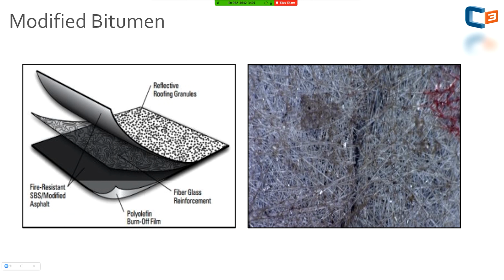So the composition there, you can just imagine that if hail struck this hard enough, you might have complete failure of the roof, it might puncture it, but likely hail is not always going to be so severe that it does that. You're going to have damage that is sustained up until that point that oftentimes is not addressed. On the right-hand side, you can see a fracturing of the reinforcement. That's what I'm talking about in severe cases where the reinforcement itself is actually compromised.